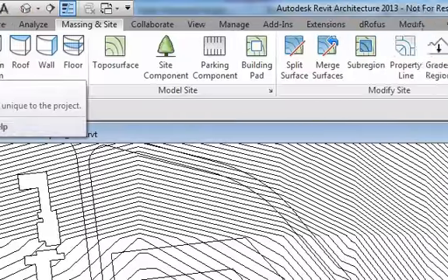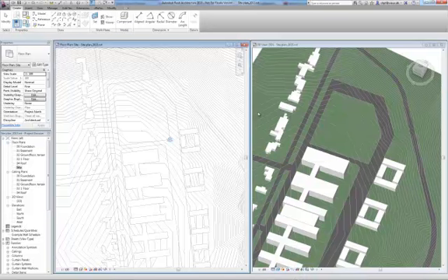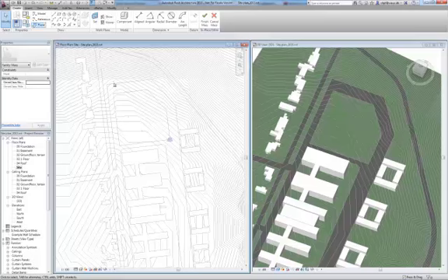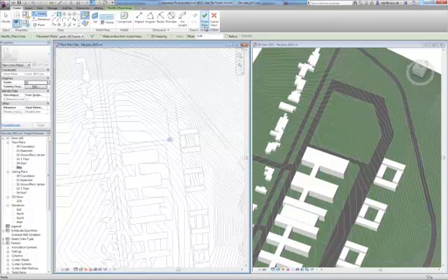So we're going to do an in-place mass. So select that tool and you can give it a name. I gave it Mass 1. And then you'll see that everything else goes grey but the area you can draw with. So all under the Create toolbar, this one here, you'll see all the tools for the mass, and as you can see you can tick to finish your mass and obviously cancel it, but that shows that you're in this massing space. So the rectangle we'll just take as a sample.